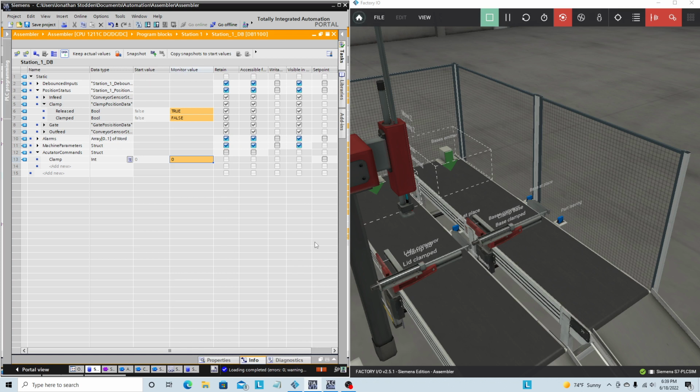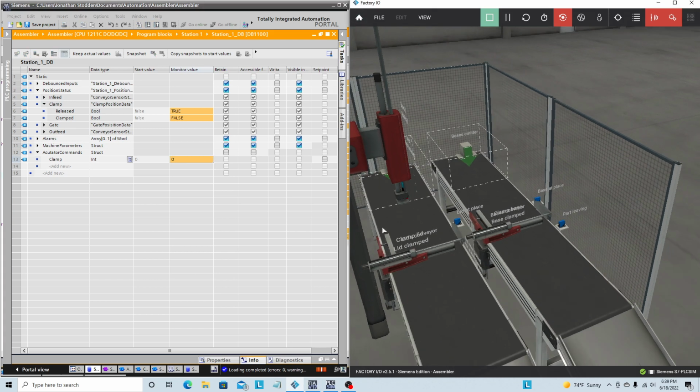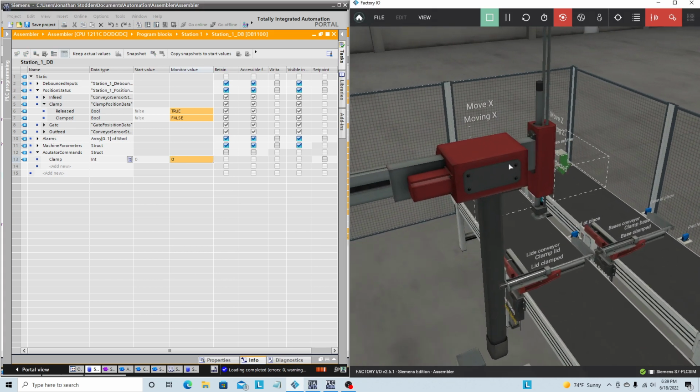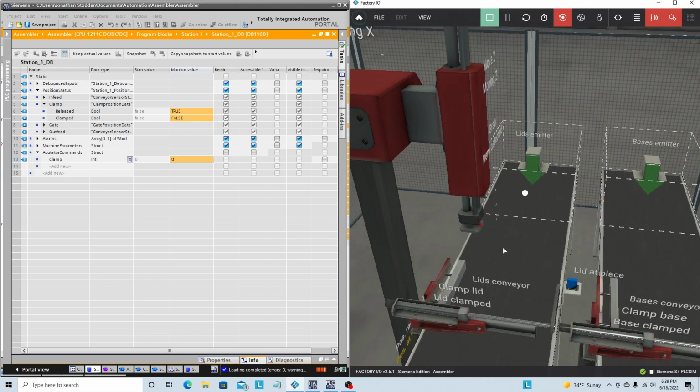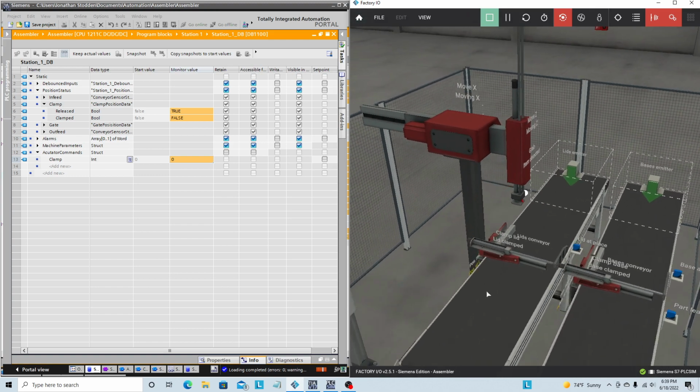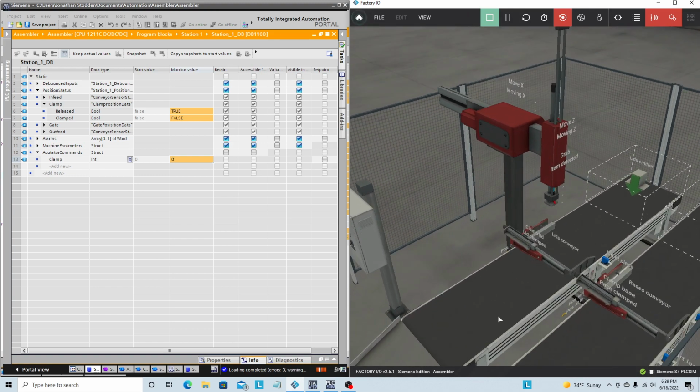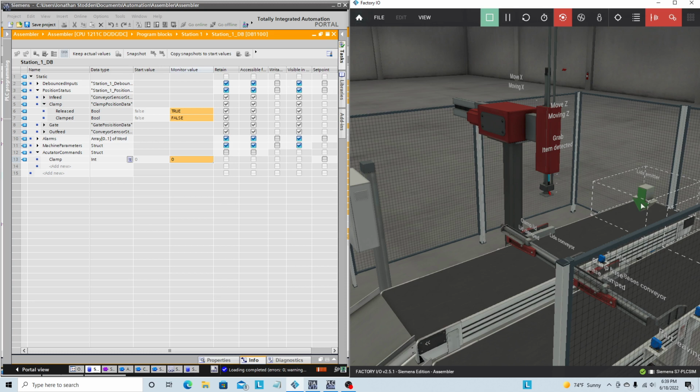And then we need to do our emitter and our conveyor. And then actually we've got all the actuator control. We still need to do positions on this guy and control of each one of these axes. I think our alarm blocks will transfer over. You know, we can use those on them. We might write some custom alarms for the conveyors, like a timeout when moving from here to here, or from here to here, and here to here.